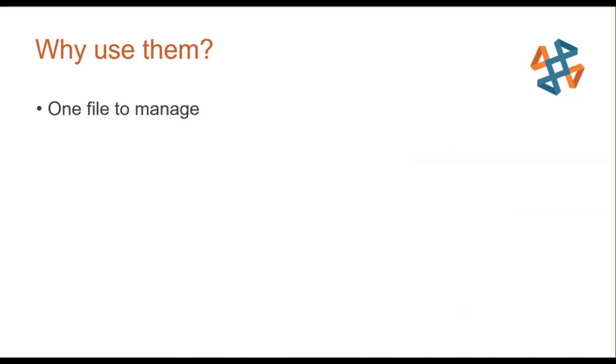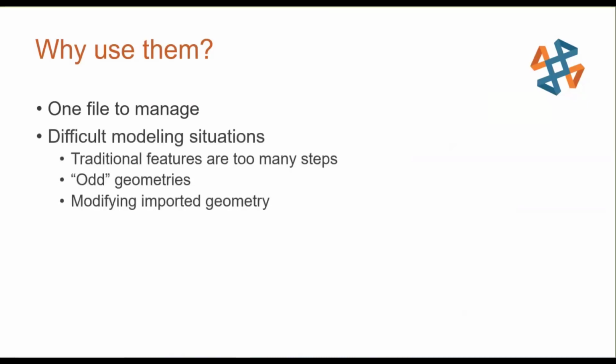Now there are commands to take a multi-bodied part, save all the bodies out to individual part files on the drive, and combine them together into a traditional assembly. So that can work as well. I like to use them, or I kind of think of these multi-body techniques as, as I jokingly call them, get-out-of-jail-free cards. Sometimes they are modeling techniques that you're definitely not going to start up SOLIDWORKS on a Friday morning and say, I'm going to use multi-body techniques today. But maybe you run into a situation where using traditional features, it's just way too many steps, or the geometry is kind of odd. I like to use them for importing or modifying imported geometry.